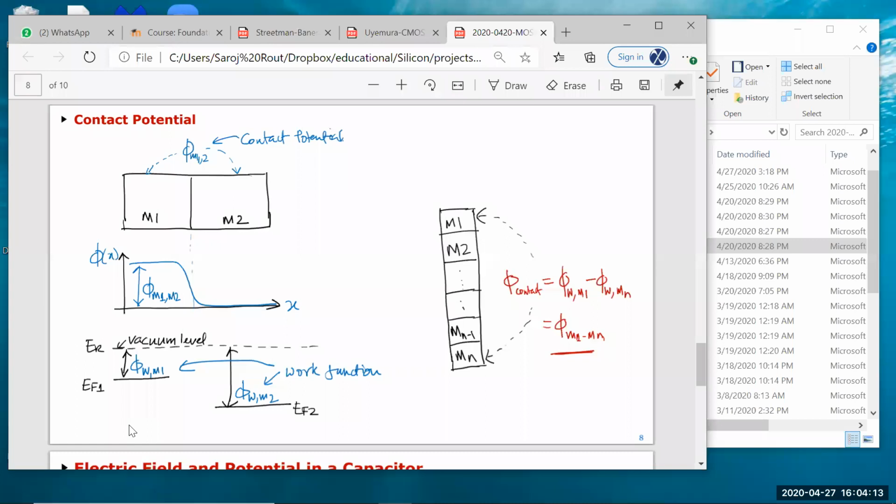Can we have a metal gate in PMOS also? Yes, of course. You can have a metal for PMOS. There is no restriction on that. It's just a different work function. So your VT will have just a different number. That's about it.